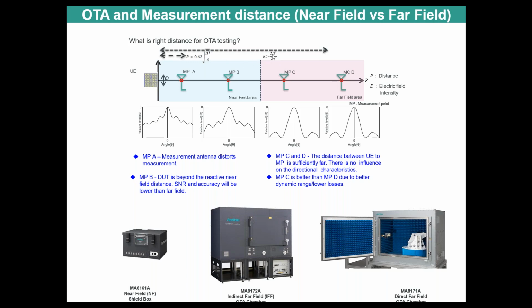The far field distance is given by the antenna aperture, uppercase D, and the frequency. As your frequency goes down, your distance becomes larger, but you have to take into account that at high frequencies your surface area becomes smaller, so you could pack a lot more antennas, and your D may become smaller. So again, far field testing is important.